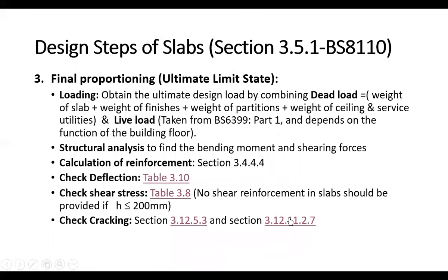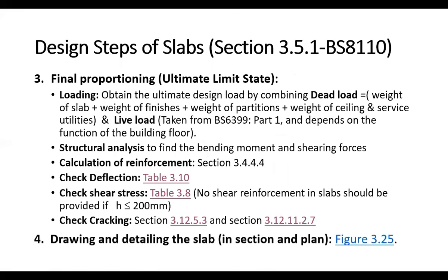So if you are satisfying the minimum area of steel reinforcement and the spacing between the reinforcement, you will be sure that your cracks will not exceed the crack width allowed by the code, and you'll have no problem in this cracking. After you finished all of this three, you finished all the design, but you have to show your design by drawings and detailing of the slabs.